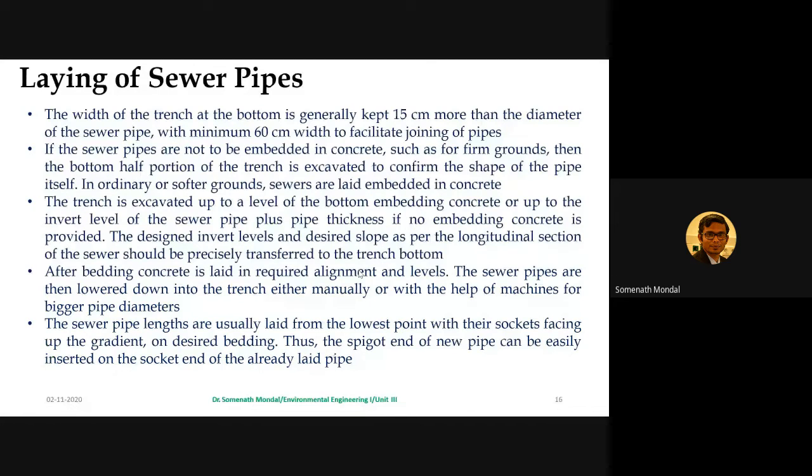However, when you have firm ground, you have to carve that ground accordingly, so that it can provide the maximum support for the pipe. So the half of the pipe has to be rested on the firm ground. This is the procedure which needs to be kept in mind. Fine.